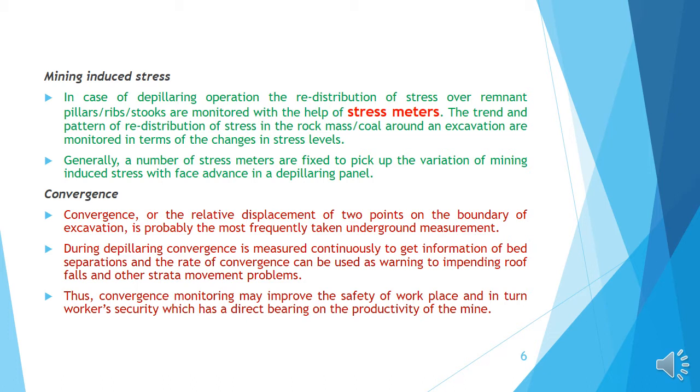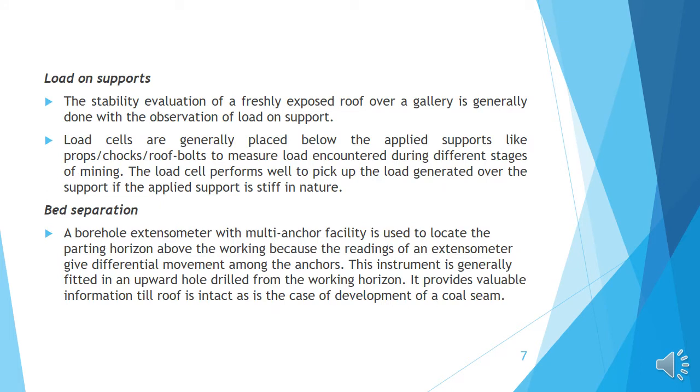Second one is the convergence, or the relative displacement of two points on the boundary of an excavation, and it is probably the most frequently taken underground measurement. During depillaring, convergence is measured continuously to get information on the bed separation. This convergence monitoring may improve the safety of the workplace. Third one is the load on supports. The stability evaluation of a freshly exposed roof over a gallery is generally done with the observation of load on supports. Load cells are generally placed below the applied supports like props and chocks to measure the load encountered during different stages.